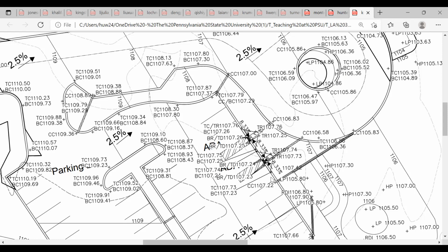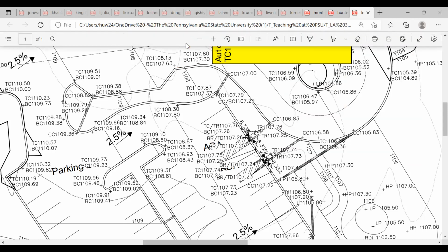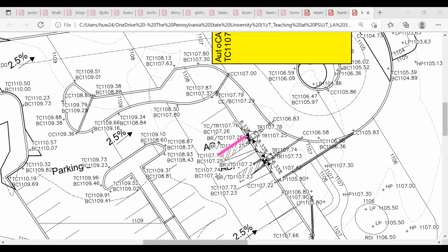One thing that I would recommend doing here is to combine these two ramps because they're so close together. That is where you get up. And then you can make this ramp more spacious. And then these are the parking stalls. That is the parking stall. That is the parking stall. So you only have one ramp over here. Then you don't need to label as much.